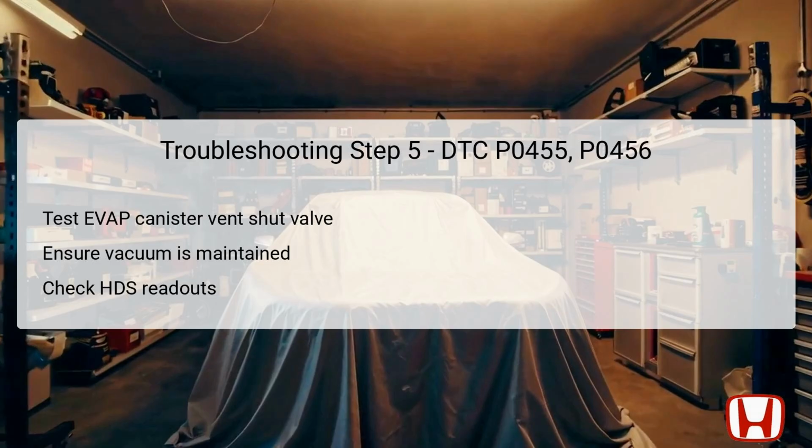First, disconnect the fuel vent tube from the EVAP canister, ensuring to plug it properly. Then apply the vacuum via the connected pump to observe the HDS readings. By toggling the HDS to the CVS on function, verify that the FTP sensor voltage again reaches 1.90 V. It is key to ascertain that the voltage reading does not exceed the set limit of 0.2 volts during the testing phase. Any deviations may indicate failure within the vent shut valve.